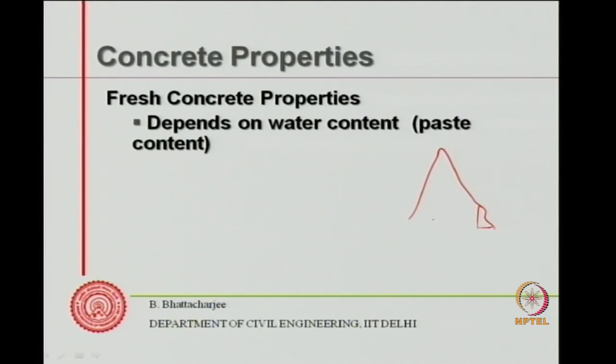Now, paste. So therefore, if I vibrate it, they may not move a little bit, but not much. But if I have paste inside them, paste in the aggregate system, this paste is easily flowable because it is more of a plastic state. So aggregates and paste together is in plastic state, and it is the paste which is easily flowable. In fact, in the paste again, the water is most easily flowable.